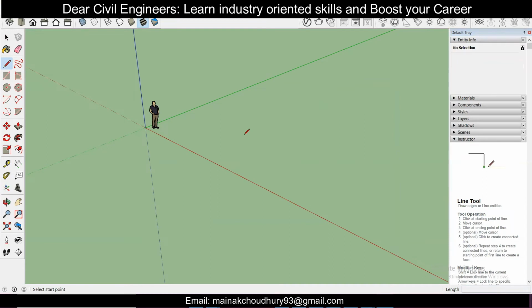Also there is a shortcut to it. Suppose you've just clicked, and if you press the right arrow on your keyboard, then it will draw along the red axis. If you press the left arrow, then it will draw along the green axis. And if you press the upward arrow, then it will draw along the blue axis. So let us take an example here.